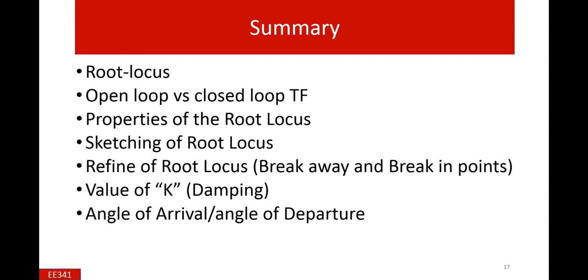In the previous example, we found that there are two or three ways to find that value. Just replace s by jω, with sigma being 0 on the imaginary axis, and we have the k value using the transfer function, and just putting in the values and solving some algebra, we then find the frequencies.